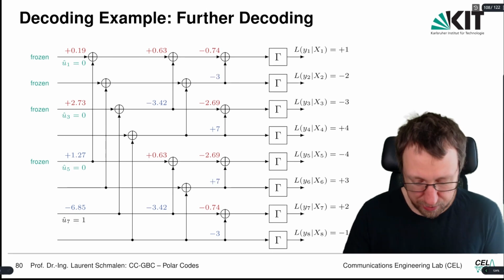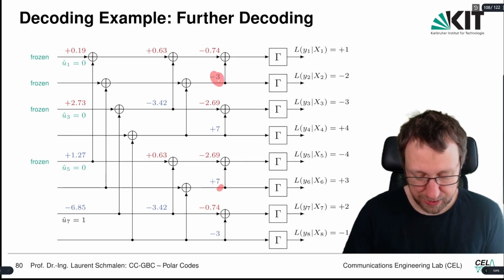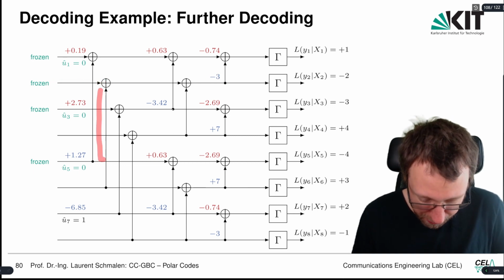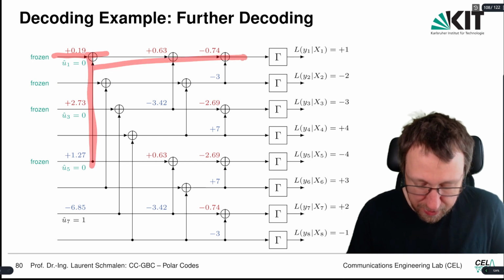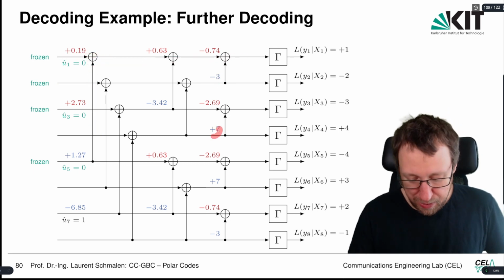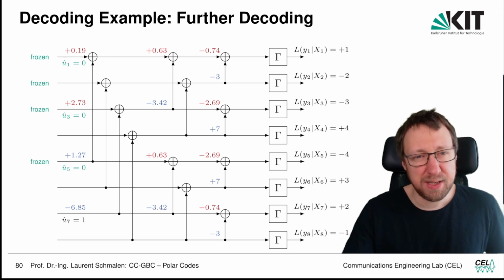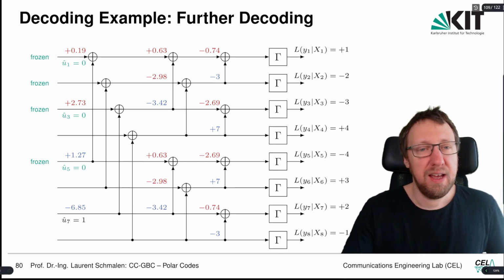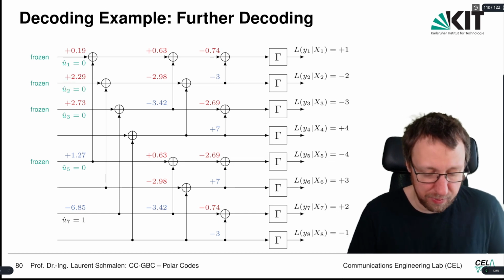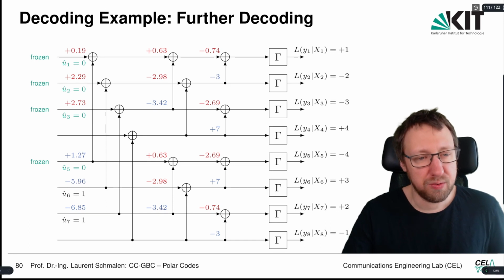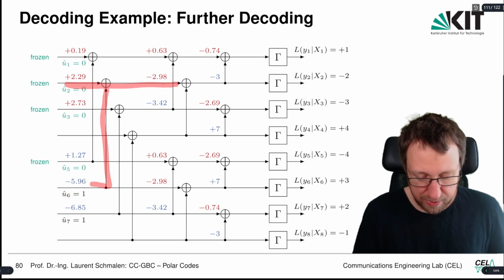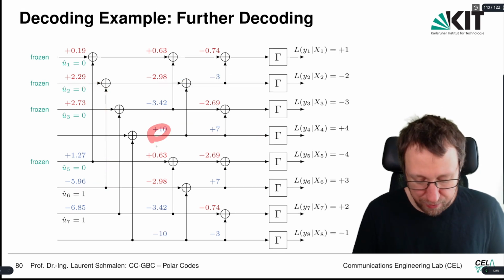Okay, first we can do the D plus decoding on these basic transformations as well. Here we also have everything that we need. We have this value and this value, and then we can continue. So we have done the D plus decodings in the first stage. Now we can do the D minus decoding, and here I do 2 decoding at a time. So we do the D minus decodings over there. Then you get this value, which is frozen, so you throw it away, and you can ripple through and slowly get the next value. Then you have another bit, and you have this value, so we can undo this basic transformation, and you get this value, this value.